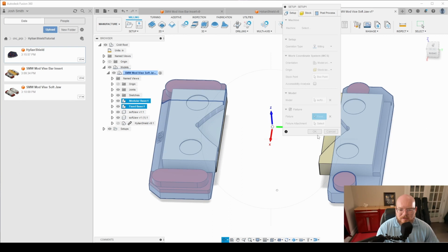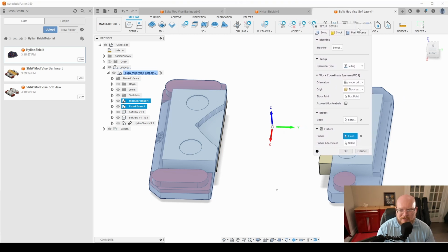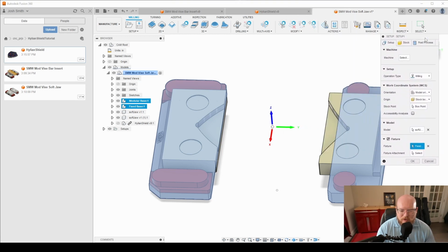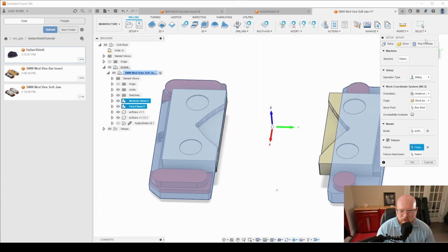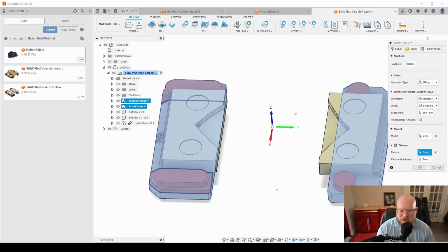So that is really going to be almost all of the Y travels that my 770 has. So I'm going to orient the vise in this horizontal fashion you see here, rather than vertically, just so I have room to slide the material forwards and backwards, to use the Y-axis cutting area I have as efficiently as possible.